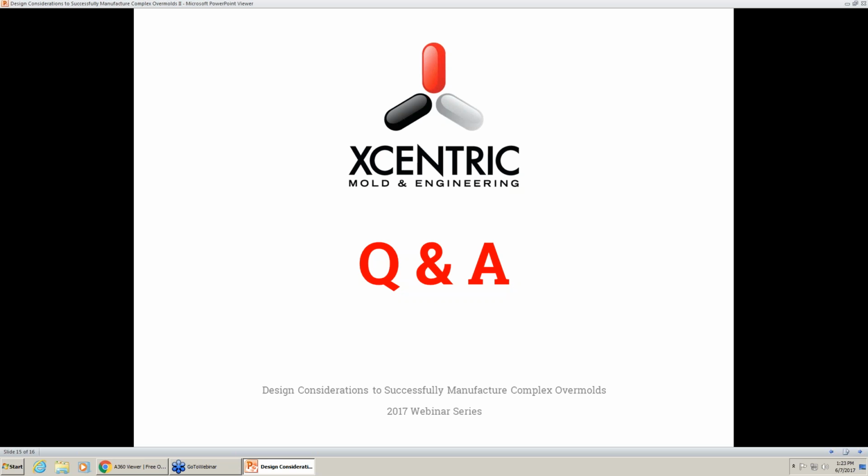We have one here. Can you overmold clear PC and get optically clear results, both in finish and clarity in the lens? What do you think about that, Steve? Well, I can say this. We've overmolded onto a lot of PC materials, a lot of optically clear materials. When it comes down to the actual overmold material, the problem that you're going to find is that when we talk about surface finishes, you can't get a polish on that actual overmold material. And the issue with that is it's not going to leave the same type of clarity that you're going to have on a PC material that's polished. So ultimately, the area that's overmolded is not going to have the same clarity that you're going to have on a rigid part that you're able to polish. Like we said before, we don't want it sticking onto the tool. We want it to stick onto the actual substrate.